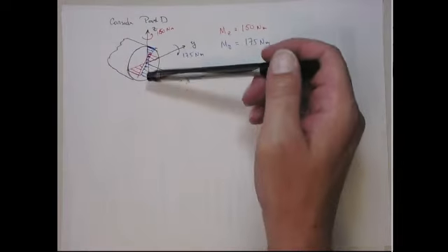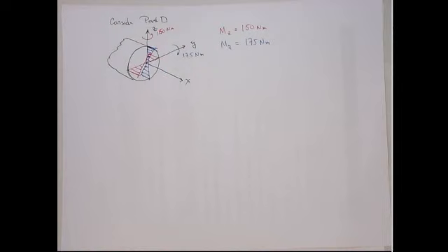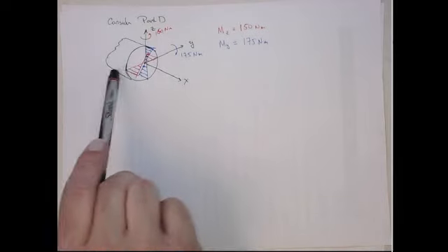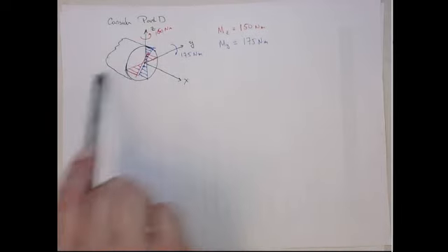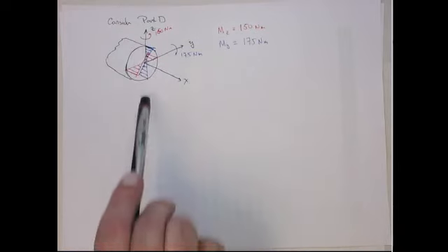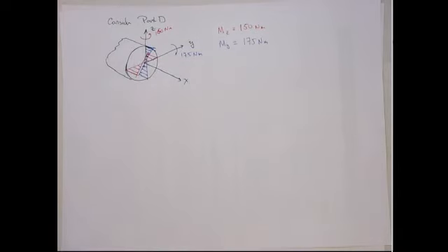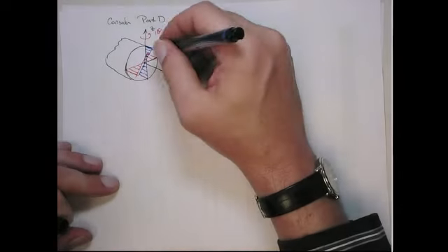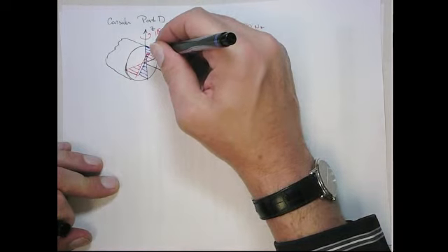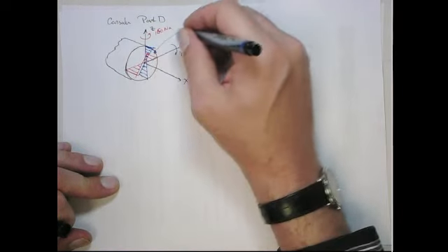And likewise, if you just consider 3 o'clock and 9 o'clock, you're going to have stress only from the moment about the z-axis, and you know that's the neutral axis from the bending about the y-axis. So actually what's going to happen here is, this is the quadrant where they're both in compression. So somewhere in here there will be a maximal value,